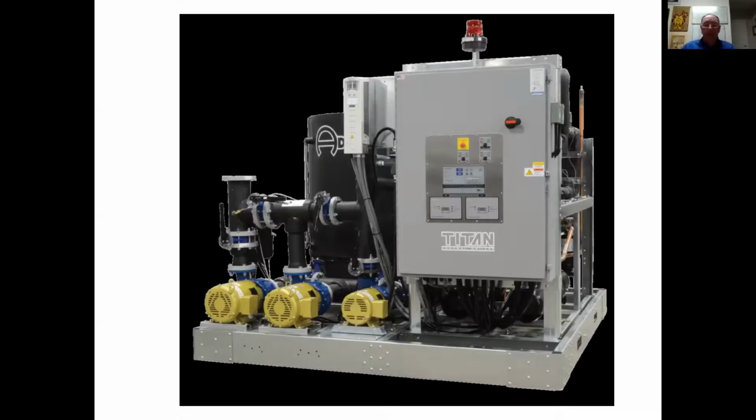We have a process pump delivering the water out to the process, and then we have the smaller pump that's delivering the warm water to the refrigerant circuit evaporators to do the heat transfer from the refrigeration system for the process water, so it goes back to your process. And then again, a standby pump to work for either the process or the evaporator pump.